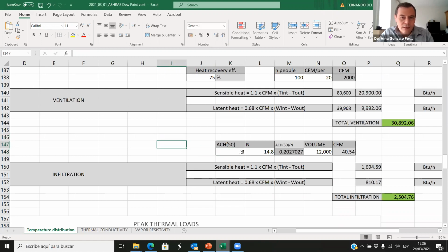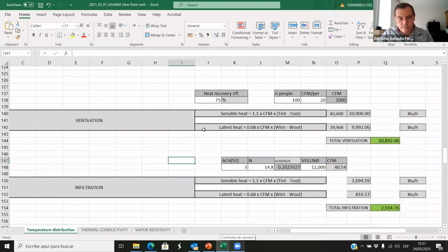Okay, so that measures the quality of the construction. And it has to do with the design for sure, but it also has to do with the construction company. So it doesn't depend on the architect itself. So if we design bad details, or especially if during the construction we are not there to make sure that all the air barriers and the thermal insulation are a continuous line that's not broken, it's very likely that we don't have good values for the infiltration ratio.